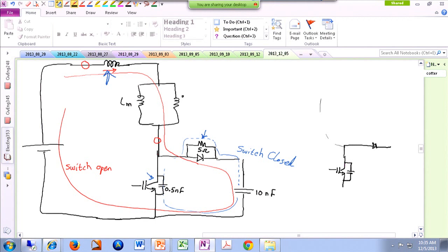When the energy comes, I'm going to charge the cap. And when it comes to discharging the cap, I just use another diode. And then it gets discharged when you close the switch. But the problem with this approach is the energy that is stored in the cap is going to get released in the internal resistance of your switch, so your switch is going to get warm.